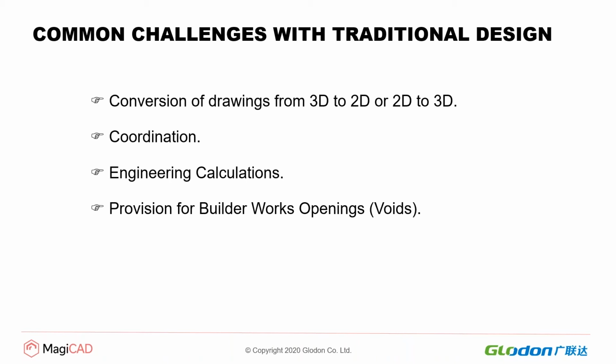So that's where we also use BIM. But when it comes to Revit or any other software, most don't have inbuilt features to do the coordination. That means we have to engage third-party software like Navisworks or Fuzor to do the coordination. But the problem is you have to export the entire model into Navisworks or the third-party software.